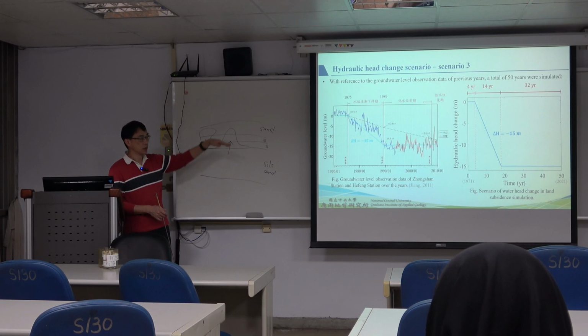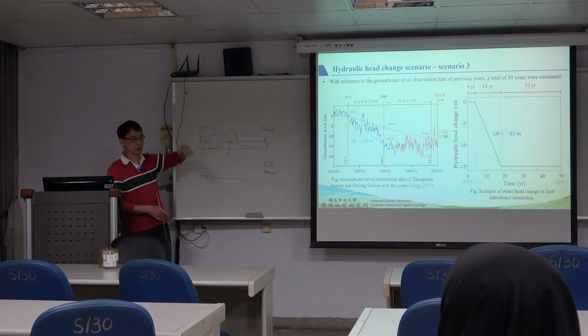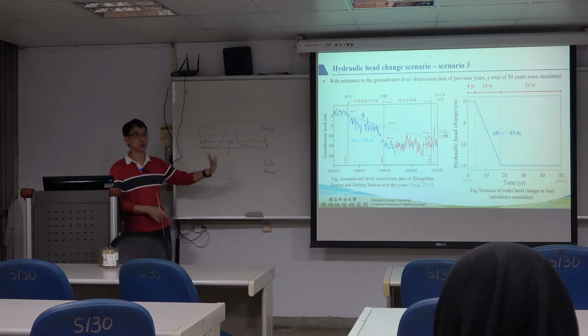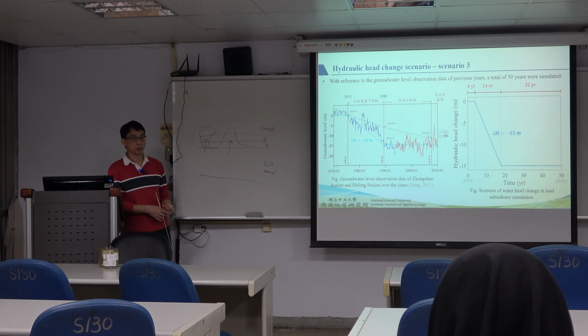Pre-consolidation head concept. In the past they were at a relatively high level, but right now they are at relatively low levels. So although we see the ground level is stable right now, the clay system will continue to have drainage behavior, because the system needs to reach another equilibrium. But clay drainage is very, very slow.